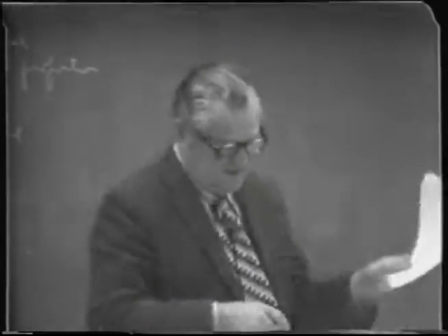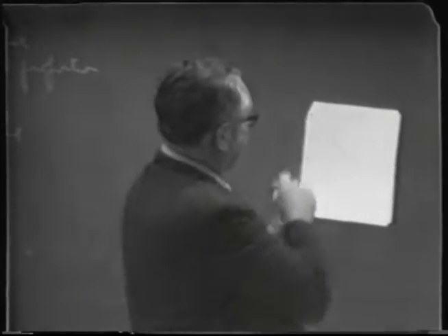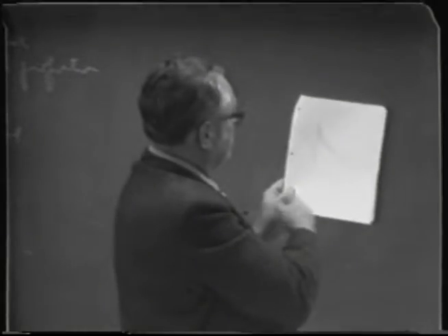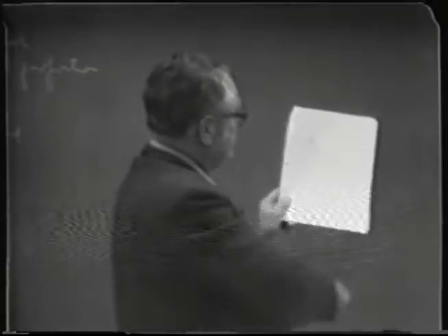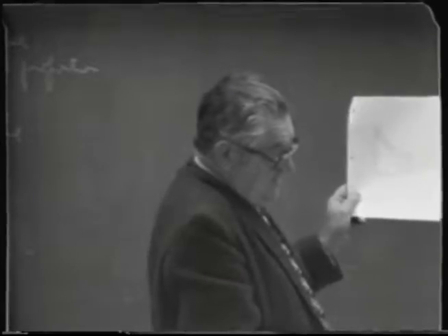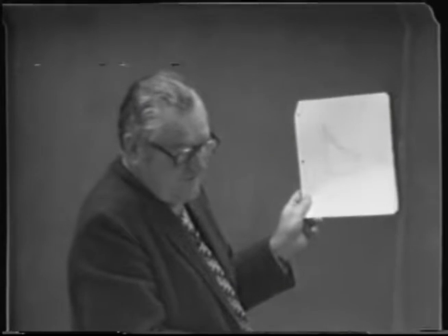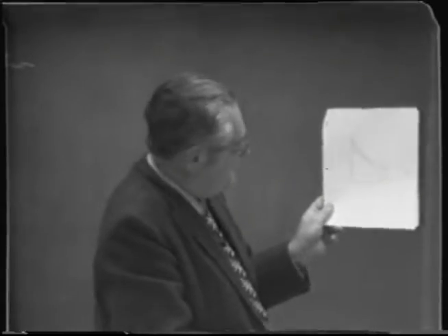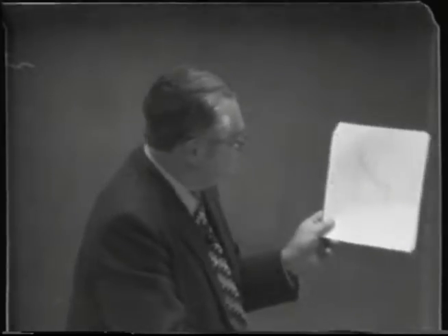On the vertical scale, this is plotted logarithmically. These are log scales. And here's percent ethyl alcohol in water plotted on the horizontal scale. Now the values used to plot these curves represent the volatility of low amounts of the particular alcohols concerned.